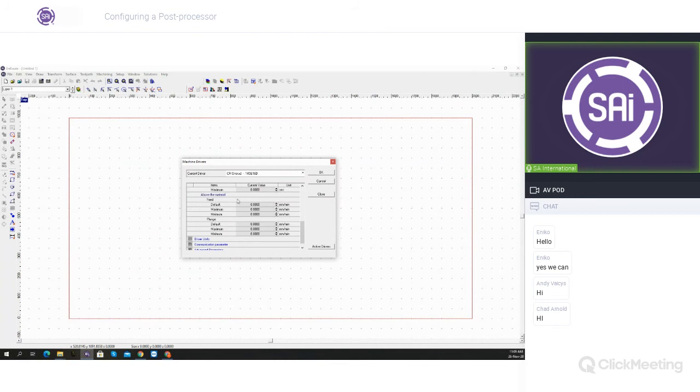Above the material feed rates, I typically do not set up here, because when the machine is moving above the material, typically it uses the fast repositioning command, which means that it will travel at the maximum speed for your machine. So for these, I would only set up the feed rates within the material.